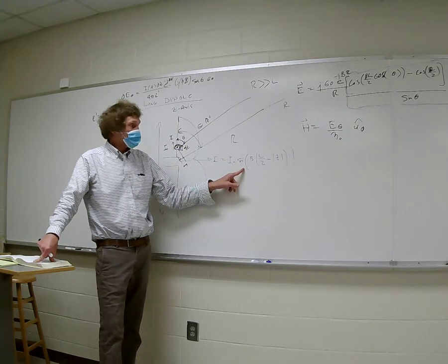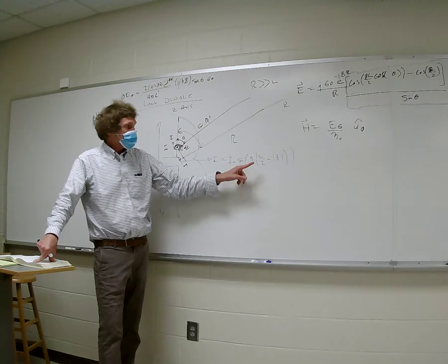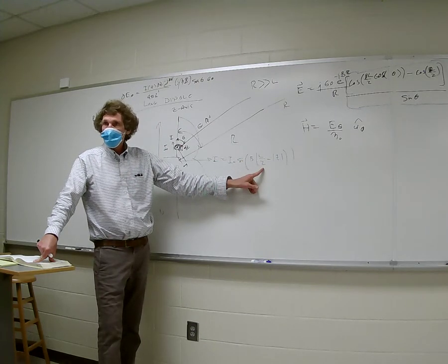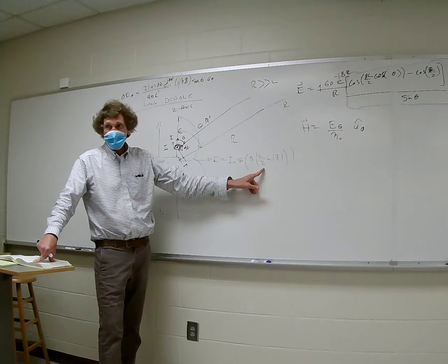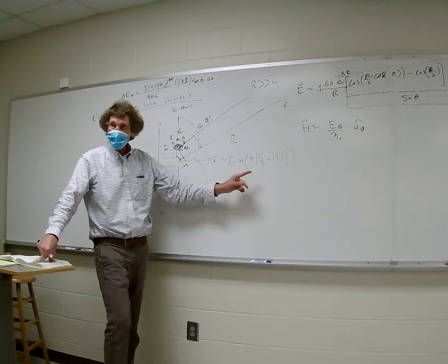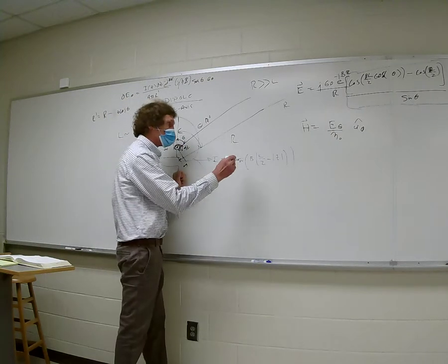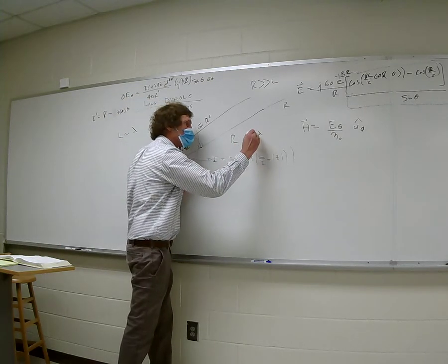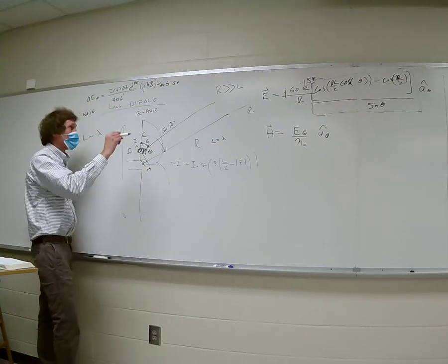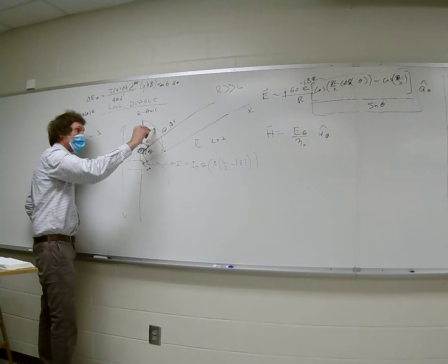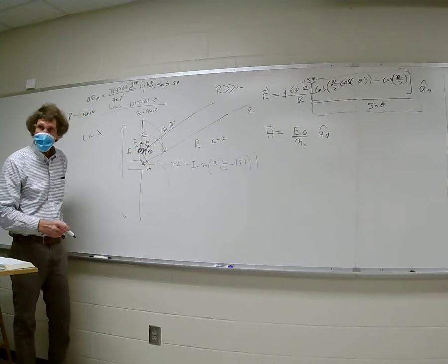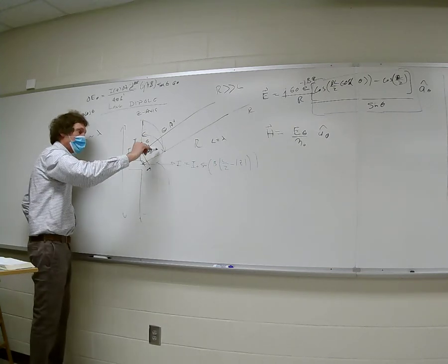Now take a look at this. What happens if the actual length right here is going to be lambda long? Just look for a second. Beta is 2 pi over lambda, right? I'll write it down. We're going to assume that L is lambda. The length of the antenna is a full wavelength. Here's what would happen, by the way. You would get this, as far as the magnitude of the current, go to an absolute zero. You would get two humps there. And if you actually looked at the current, the actual current would do this.